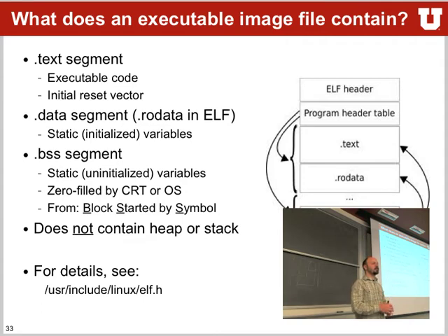So I'd say that things like int variable name do not have an assembly equivalent. It just is in your C code, not in assembly. Well, it depends. Yes, it does depend. Sometimes that's when stuff becomes complicated. So the compiler decides, do I really need a location somewhere or not? For example, global variables that you're using, even if they're int something, will most likely be a 32-bit integer, and they will sit somewhere in memory. So it will create a BSS entry for it, and then later on it will just use that particular memory location wherever you use this variable. You will see that all in your code next week.